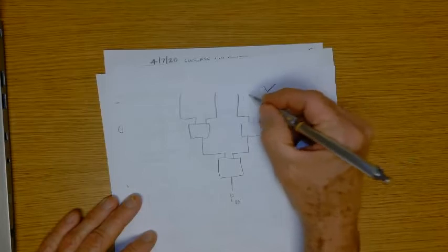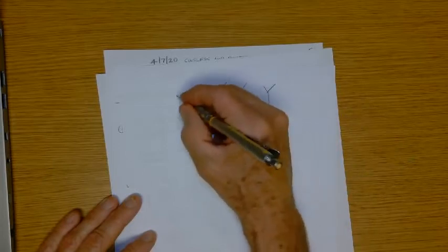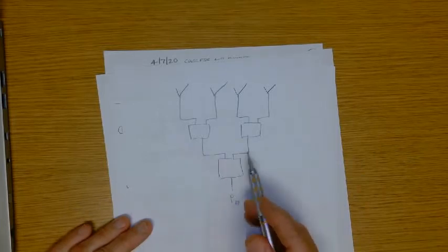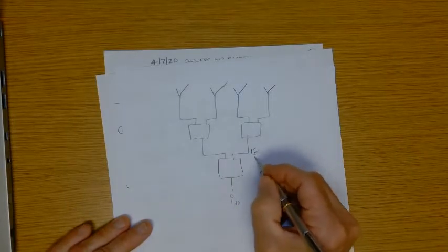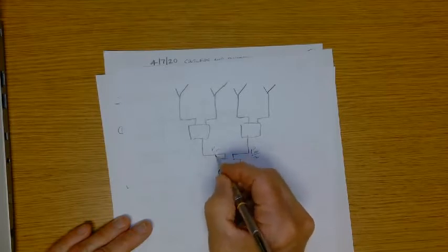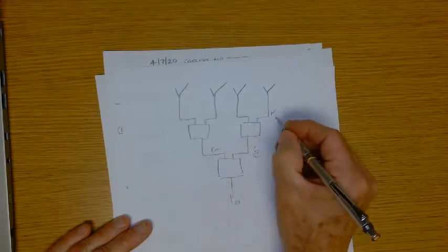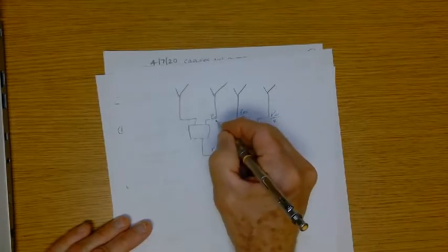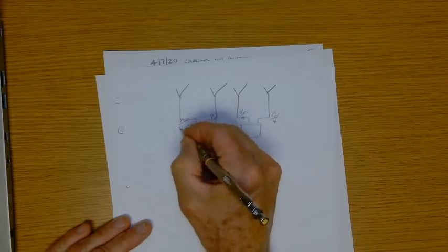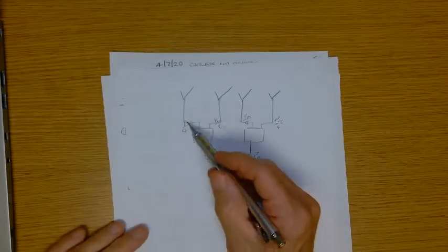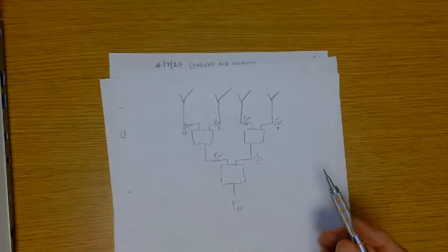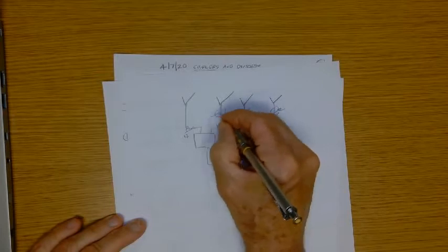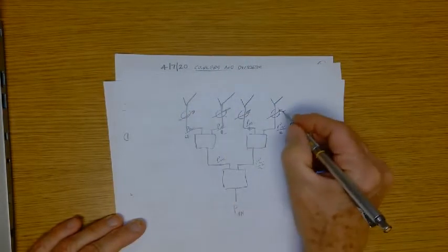I think the intent is shown. These are antennas now. So essentially, power half this way, half that way, Pn over 2, Pn over 2, and then it splits again, Pn over 4, Pn over 4, Pn over 4, Pn over 4, and so a quarter of the power goes to each transmit antenna. We might also have some phase shifters in here.